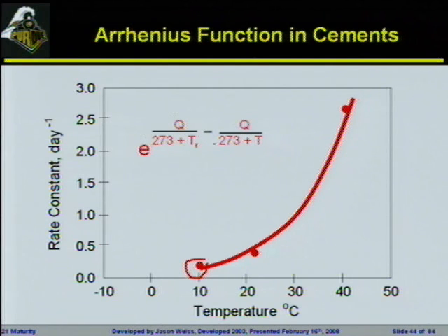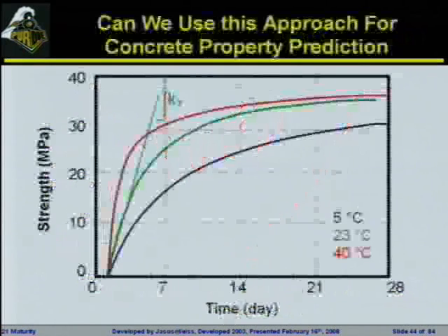So you will see a modified version of this Arrhenius equation going in, because we're typically talking about comparing whatever rate we want at any particular temperature to the rate at the reference temperature. So we will plug our temperature in degrees Celsius. We've got our 273 to convert us over from Celsius to Kelvin. We've got our activation energy divided by our gas constant. And then we will have the temperature wherever it is that we want to know our particular concrete, so that we are looking at a difference in the temperature in that particular range.